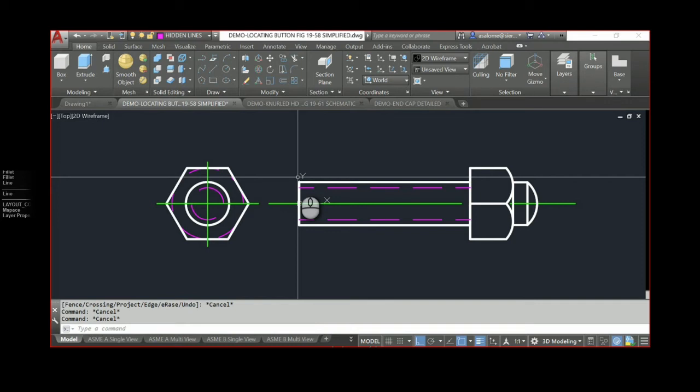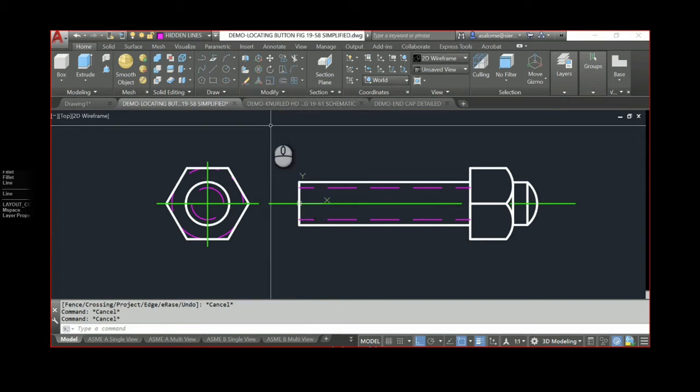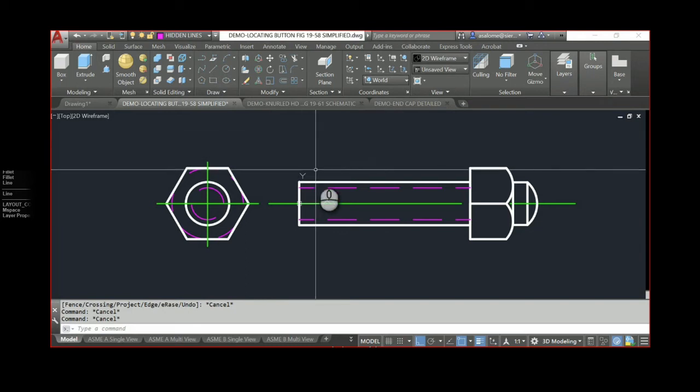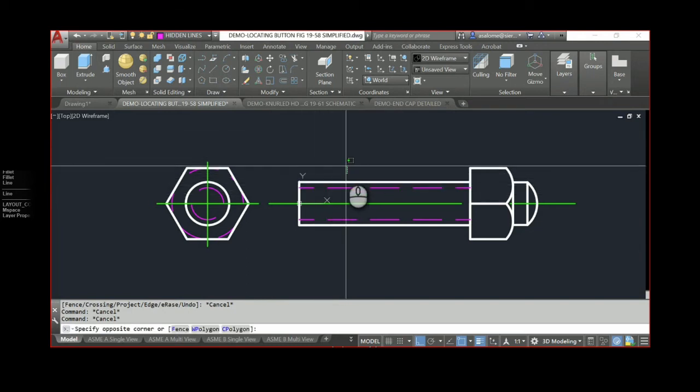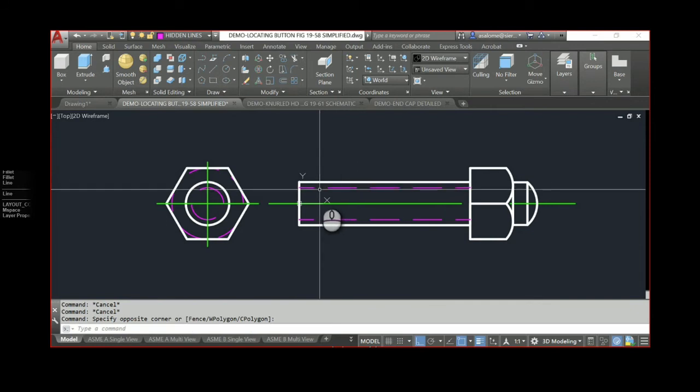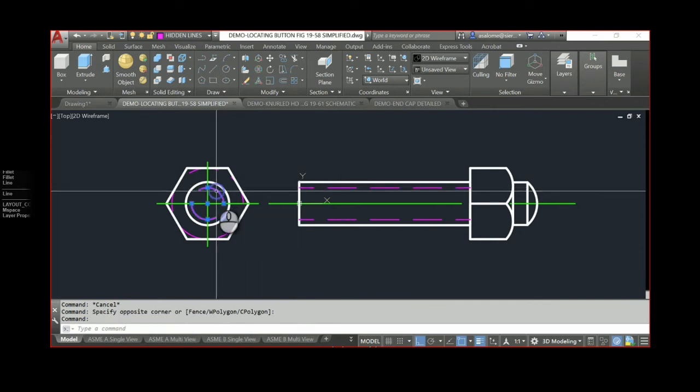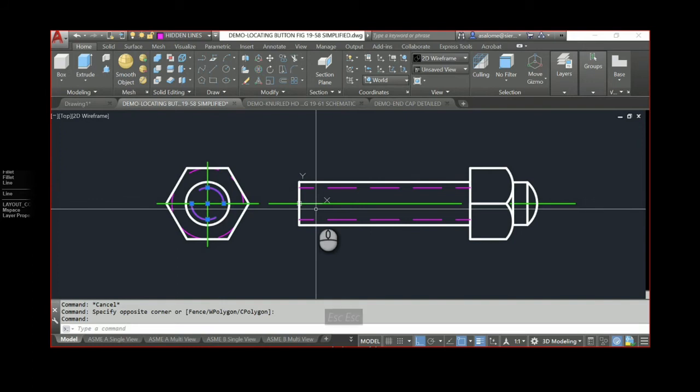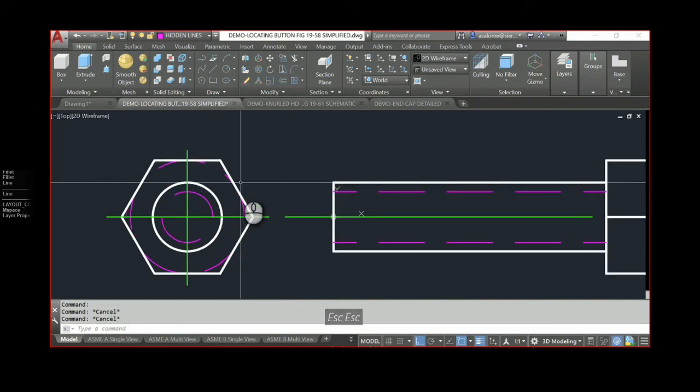It doesn't get any easier than that. That's the easiest kind of screw threads that we can show on a drawing. They are allowed per ASME. And they tell the viewer, between looking at this and knowing that, hey, that hidden line there is something, that this is a tapped hole. Now, think about why that makes sense.